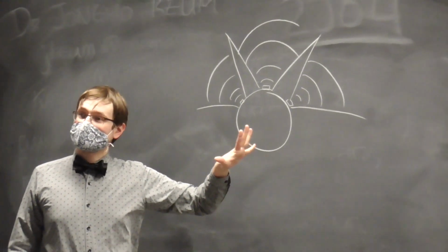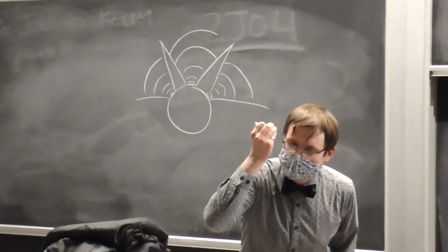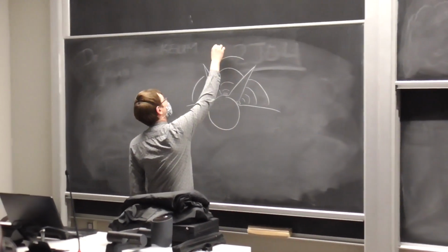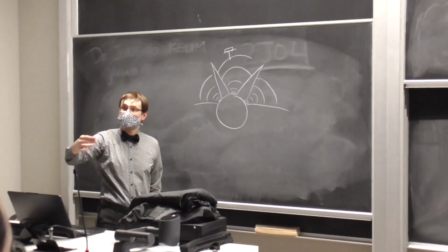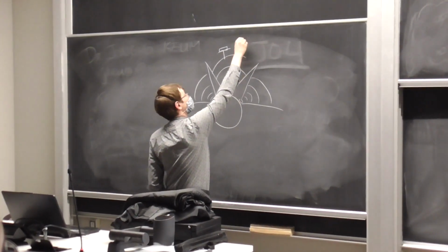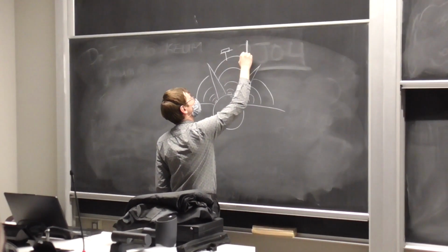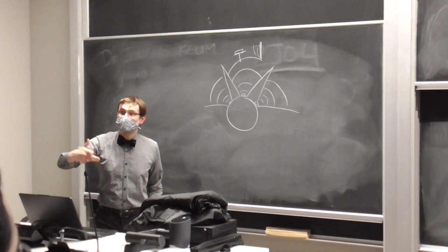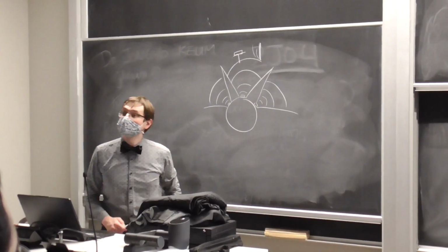Now that's going to break down at a certain point, and ultrasonic sensors are not the most reliable way of sensing distance anyways, because if you have an object that's perpendicular to the oncoming wave, then that's obviously going to work the best, right? But if you have something that's thin and oblique, when the waves hit that, they're going to glance off it, and then it's not necessarily going to reflect much back into the ultrasonic sensor, so something like that might be invisible to it.